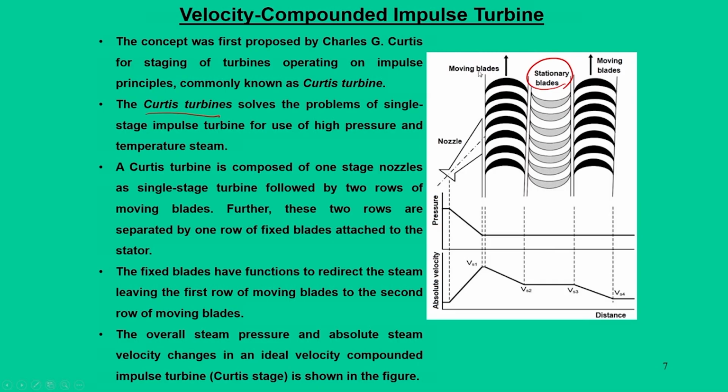And of course, at the entry stage the entire steam or power is supplied through a single nozzle or an array of nozzles. Same concept is applied here, but in a pressure stage, pressure drop occurs only in the nozzles; after that the pressure remains constant.